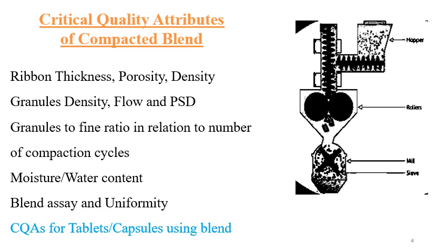Whenever you are working on tablets made with the roller compaction process, weight uniformity, hardness and disintegration are very critical as in-process critical quality attributes. Then dissolution is an important parameter for tablets and capsules which are prepared by the roller compaction process.